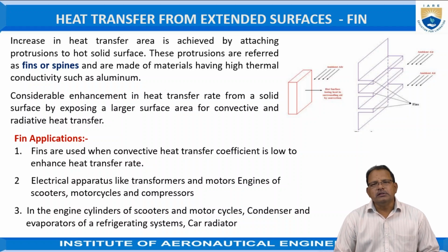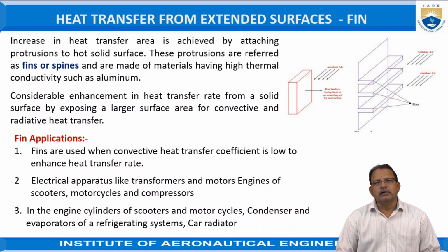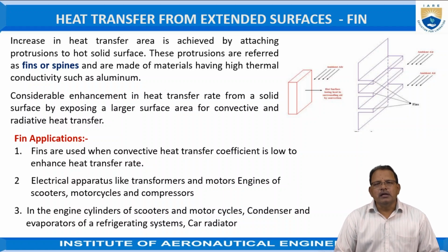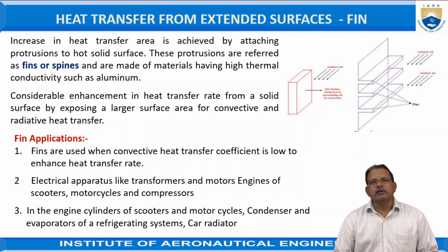Generally, these projections are made of materials with high conductivity, such as aluminum. Due to the increased thermal conductivity as well as the surface area, the heat transfer from the hot surface to the cold liquid can be increased considerably.